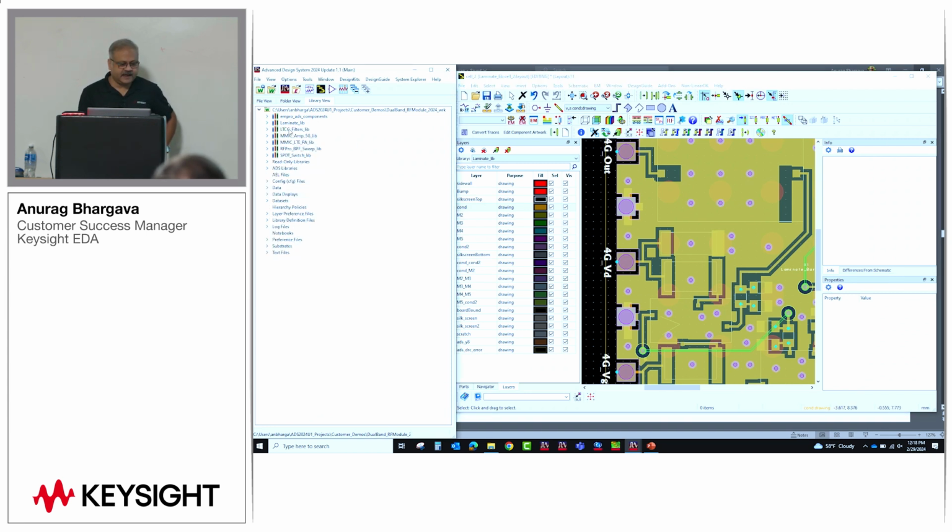Now, each of these libraries has to be mounted in a specific manner. So I want to place this 5G amplifier. You could either do a flip chip mounting, or you can do a bottom mount and then use a bond wire to assemble. So how do I tell ADS that this design, when I place it on this laminate, has to be flip chipped? So simple. Let's look at a smart mount.